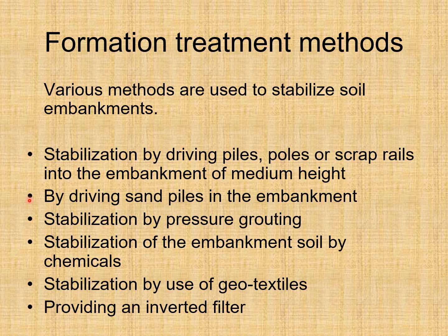By driving sand piles in the embankment. Stabilization by pressure grouting. Stabilization of embankment soil by chemicals. Stabilization by use of geotextiles. And the other possibility is by providing an inverted filter. So in this way we can treat the formation.